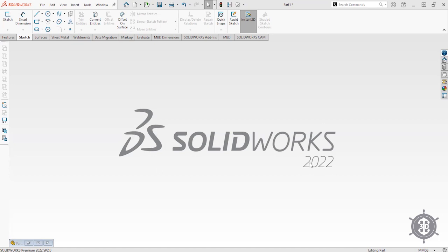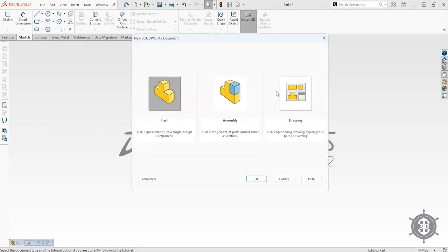So now this is the screen which you see as you open SolidWorks Professional. Now moving on to Sketch. Now clicking File, New. Now we see these three options. Assembly is advanced stuff. SolidWorks drawing is advanced stuff. Currently, we'll be doing only part mode. So click OK.